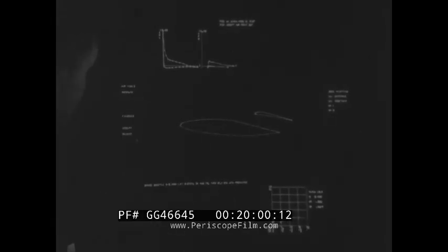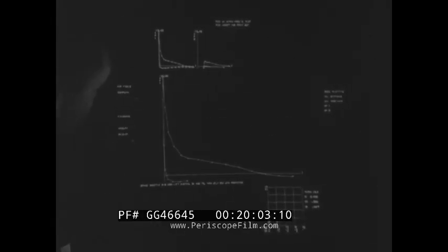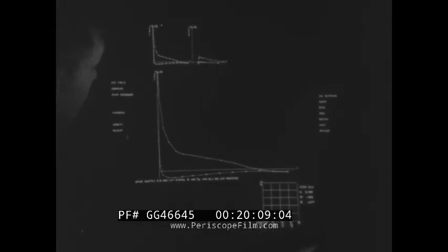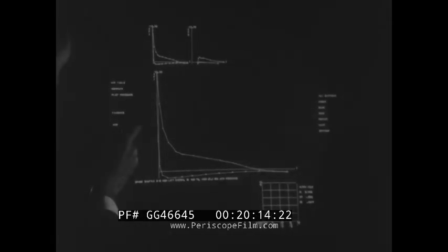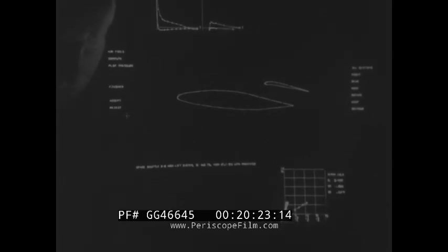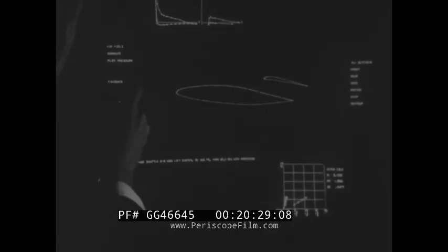Now let us take a closer look at the pressure distributions on the wing surface. Now we can formulate the next geometric change to the high-lift system. We can display, translate, rotate, or change contours and obtain a new set of aerodynamic data. We repeat the process until we obtain the required data or the desired level of lift. Using Digigraphics, we have been able to accomplish tasks in 20 minutes that under normal circumstances would take 4 to 5 months and involve expensive wind tunnel models and tests.